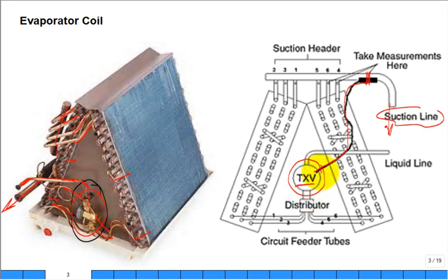It's just another acronym. And here they have it in 1, 2, 3, 4, 5, 6, going into 6 different places, collected in 6. So this illustration shows 4 pathways. This one shows 6 pathways through the evaporator. Okay. Why do they call this the liquid line? Because the state of the fluid in that line being supplied up to the expansion valve and then immediately after it in the evaporator is in a liquid state. What is the pressure in that liquid line? High or low? High pressure. It's high pressure.